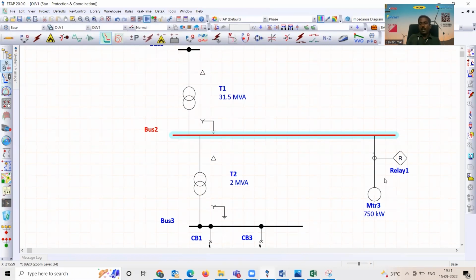So which means if you want to really fine tune your earth fault setting, then what you need to do is study the unbalance of the motor current during the starting using PSCAD. From that, get the worst case unbalance and time plotted, and above that you set your SEF 51 setting. But literally it is technically impossible and it is time consuming.